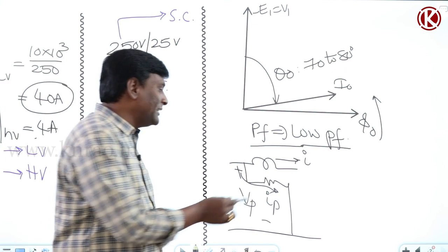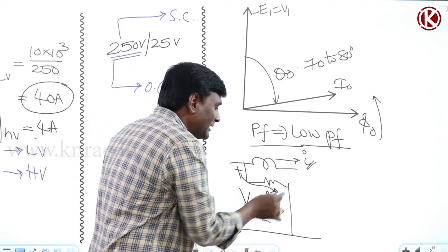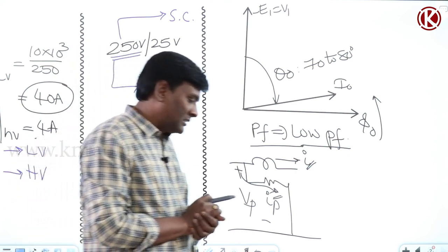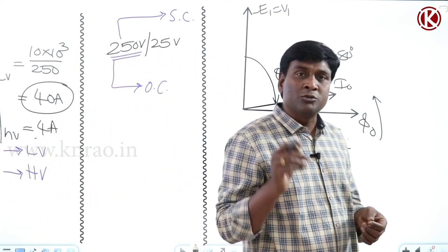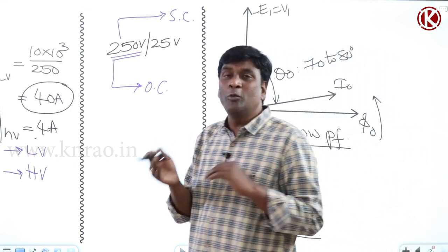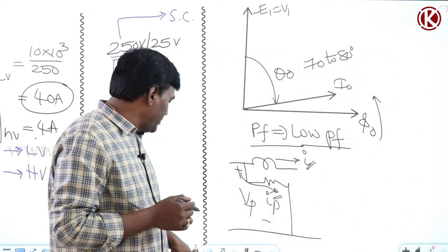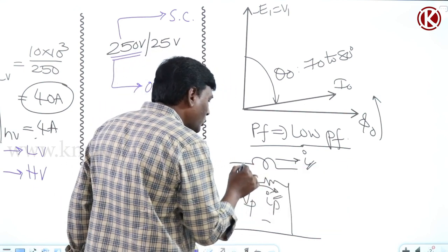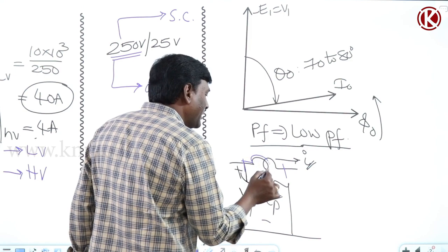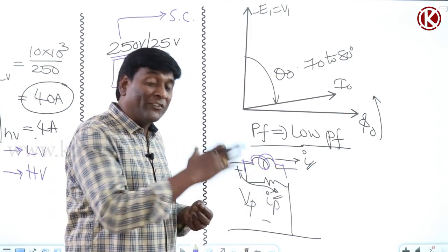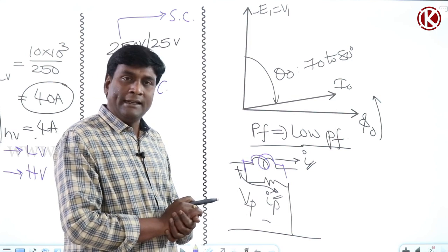But under low power factor condition, when the angle is more, the deflection torque developed between this I component of current and the IP component of current is going to be less. So in order to compensate under low power factor condition, in your measuring instruments we add one more current coil in parallel with the existing current coil, to improve the deflection torque to show you the reading.